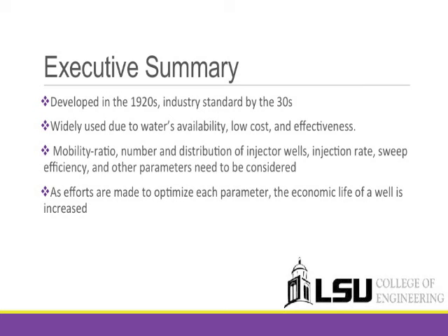Popularity of the technique grew due to the fact that water is inexpensive, readily available in large quantities, and efficiently raises production while maintaining pressure. When engineers design a water flood for a specific reservoir, there are many factors that come into play. They have to take into account mobility ratio, the number of injector and producer wells, injector well patterns, injection rate, sweep efficiency, and water additives.